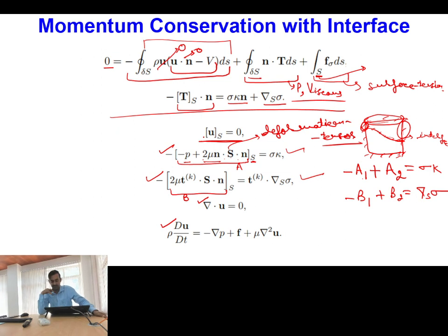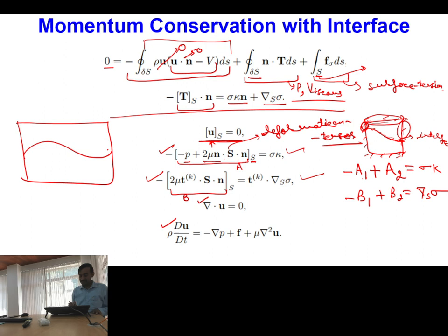All are clear with this point? So here both these conditions are included in a single point. How? Because I am writing u vector. Now this vector will be having two components. One will be normal to the interface, one will be tangent to the interface. So both the velocities in fluid 1 and fluid 2 are same. Point is clear? So the meaning of two fluid approach is, say at any point of time your interface is something like this. So what you will be doing? You will be having so many cells like this.